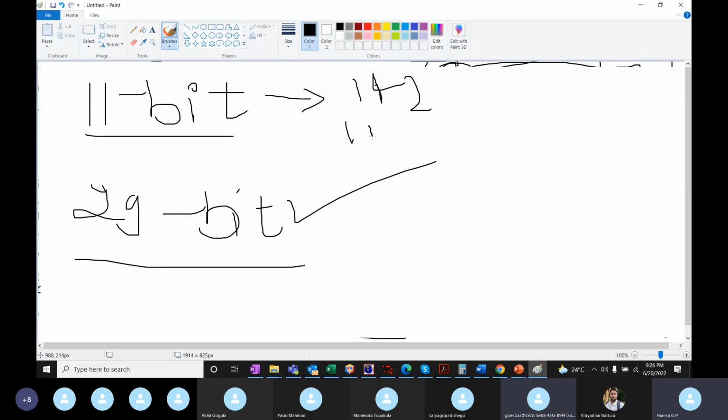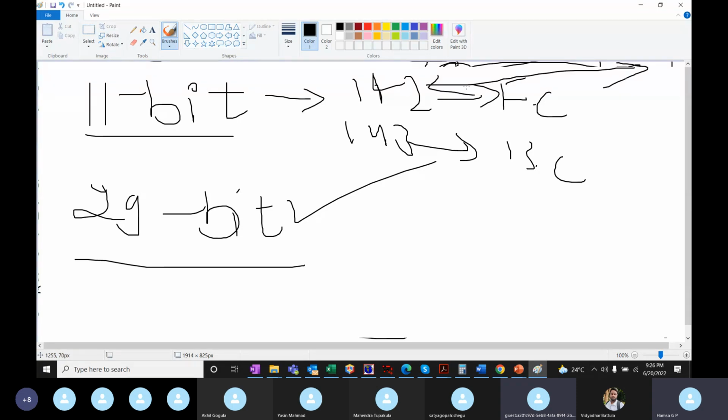142 we have seen, 143 we have seen. Remember, it's the front camera information and it provides the back camera information. After the identifier, whatever comes is the data. We have not gone to the data itself still. We are still in the identifier. So why do you think 29-bit is important or required?